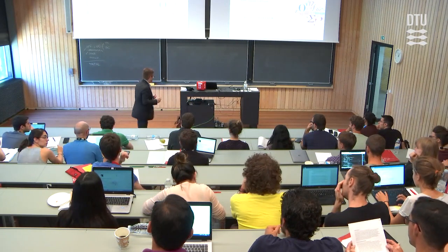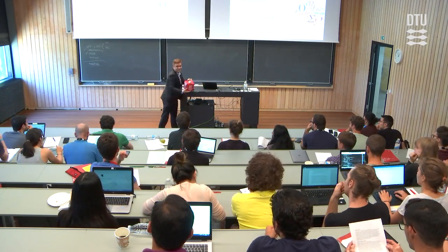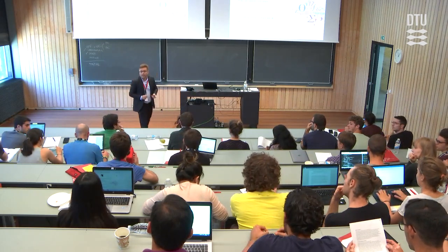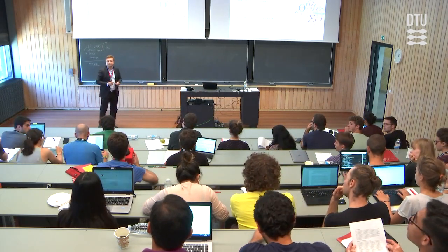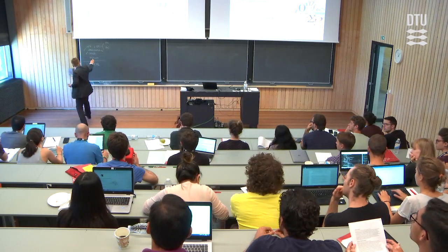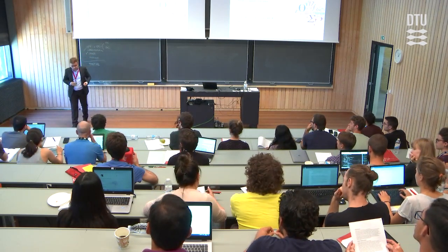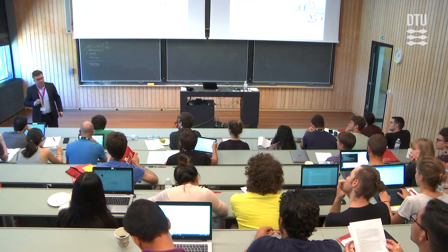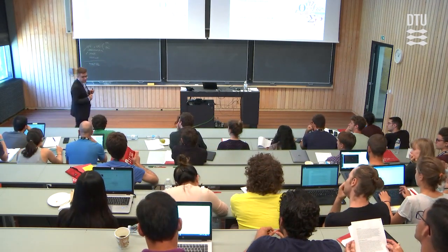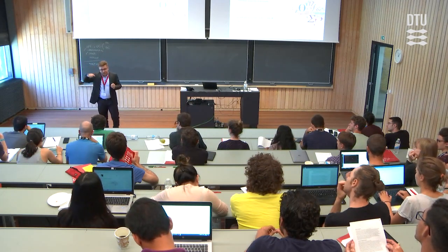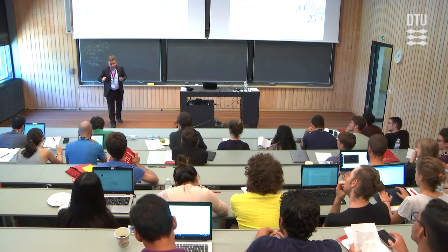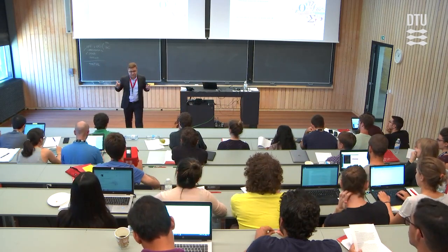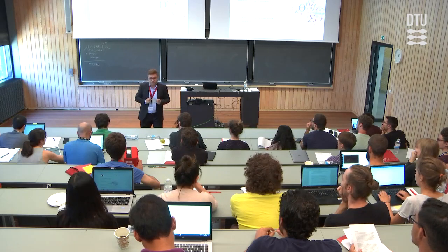Dirk? Oh, that's my turn. Okay. I'm not sure if one would consider the network topology in the market clearing. Yes, when we clear the market, at least in the US, we have the network constraints. In Europe, yeah, we have a simplified version, we call it zonal. So we just see the network capacity constraints between the countries, but still it's kind of a simplified version of the network.